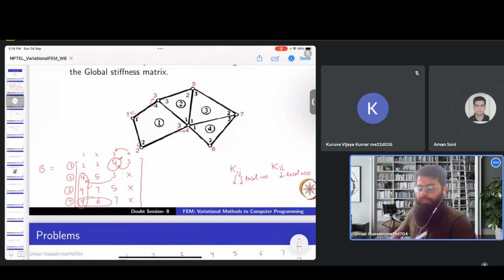If we have larger meshes, when we are assigning the numbers to the nodes, we usually follow some path, starting with 1 2 3 4 5 6 like that. That's why the nodes which are far away would correspond to off-diagonal elements, far from the diagonal in the global matrix.